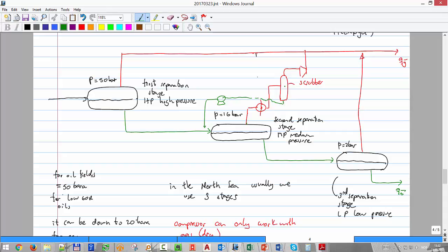Okay, exactly the same. So the trick is I lower the temperature, induce condensation, then I take out that liquid, and that liquid won't be at the saturation point anymore. Okay, it won't be so close, and then I can just introduce it to the compressor. Yeah, so let's copy maybe that.